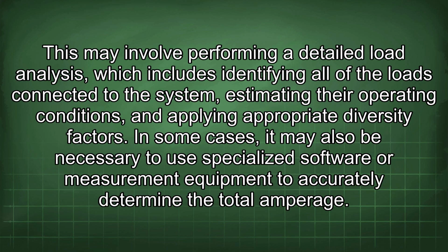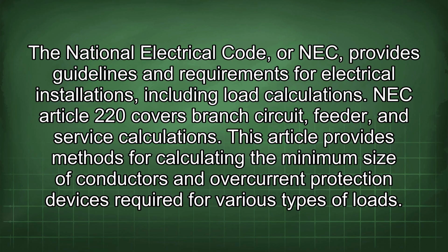This may involve performing a detailed load analysis, which includes identifying all of the loads connected to the system, estimating their operating conditions, and applying appropriate diversity factors. In some cases, it may also be necessary to use specialized software or measurement equipment to accurately determine the total amperage. The National Electrical Code, or NEC, provides guidelines and requirements for electrical installations, including load calculations.